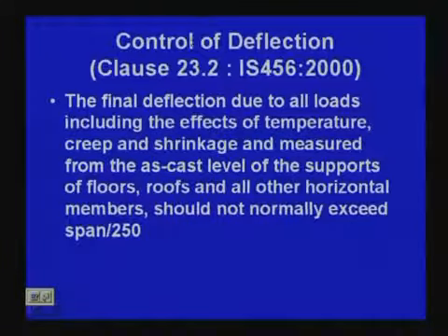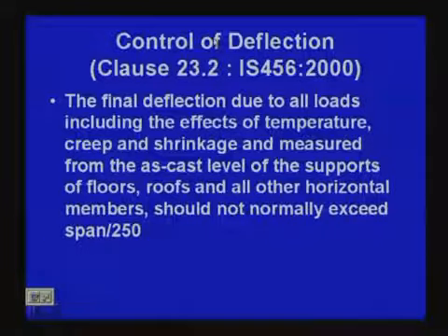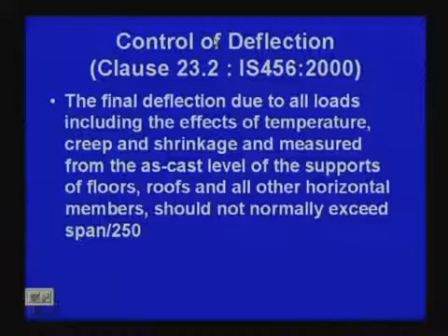One more part that is very important, because this is the one that will give you serviceability. So far whatever I have been talking about is actually the limit state of collapse. We are talking about flexure here for beams as well as for slabs, but there is one more part, that is the serviceability limit state, so that the users will not feel any discomfort.